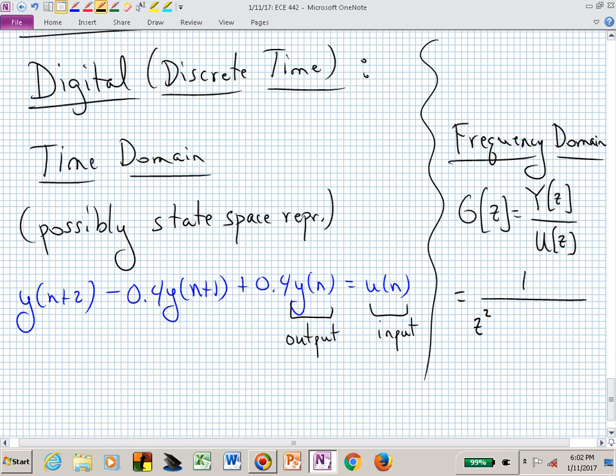Now you just have to sit there and wait one delay and then pop out the other side of that delay block. So these unit delays are maybe easier to think about than these integrals that you're used to thinking about for block diagrams. But now we have this interconnected system of unit delay blocks with gains, delays, and summers, and you just are having to sit there and wait until the next time instant, and then you pop out the other side of that delay block.